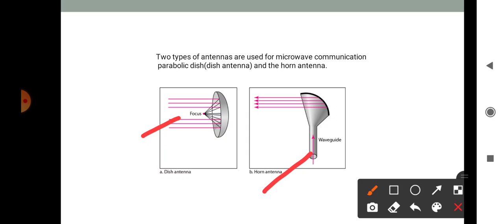This horn antenna derives its name from its characteristic flared appearance, and the flared portions can be square, rectangular, cylindrical, or conical. The direction of maximum radiation corresponds with the axis of the horn, and the horn is pointed toward the center of the dish reflector. The use of a horn at the focal point of the dish minimizes the loss of energy around the edge of the dish reflector, and horn antennas have excellent gain and directivity.